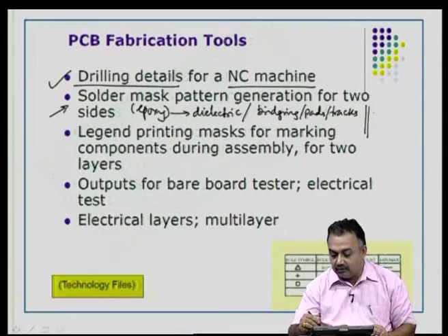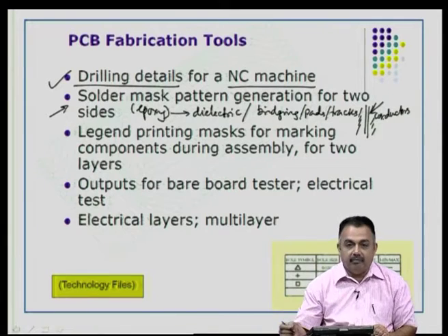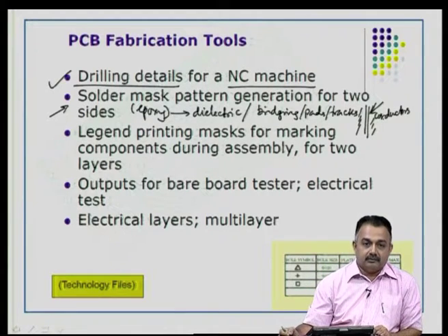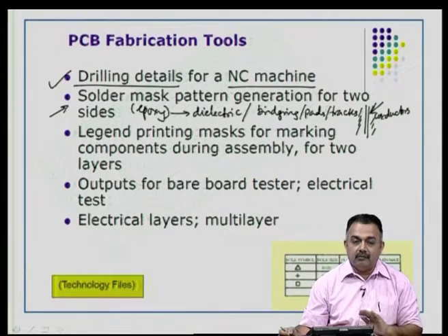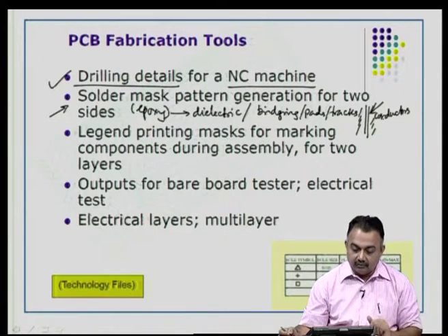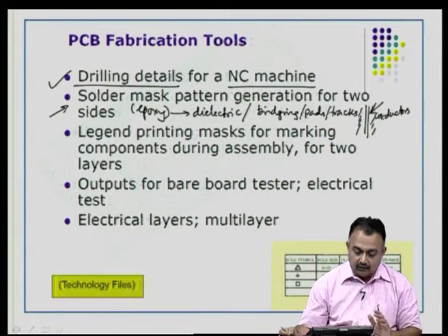So, if you imagine two conductors here, then imagine there is solder mask in between these conductors and the outside areas. Obviously, it provides a better electrical performance. And imagine in a high density circuit, these lines will be very close, and also the pads will be very close to each other. A pad will be very close to a via structure and so on.